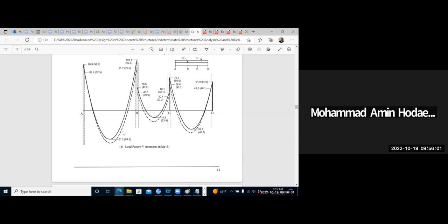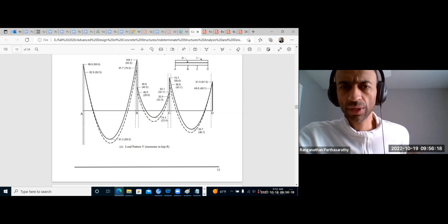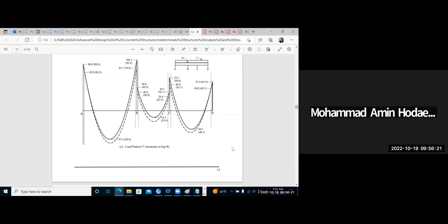And for comparing the section, the concrete section that you use, 0.85 f'c a b for the formulation. Can you compare this to that part we were talking about, serviceability, and where we are on the curve? Because we are supposed to use nonlinear capacity, and our load should be much more than serviceability, but where are we on the curve?